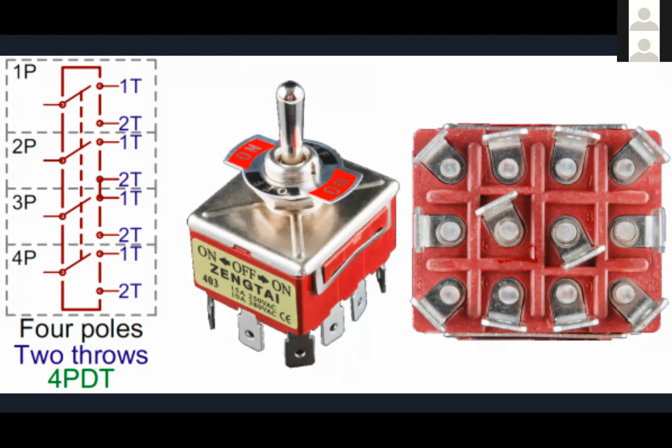8. It looks like it's 8, but it's not. It's only 2. 2 times 4 is 8, and there are 4 poles in there. So you're switching 4 things at the same time, but each of them can only be switched into 2 different positions. And so in this picture that Arushi is showing, those 2 ons are the 2 different positions that you can switch to. Now this one might have, I don't know because I would have to purchase the switch, a middle position, which it appears that it does because I think I see the word off, and that's pretty unusual that that's there.